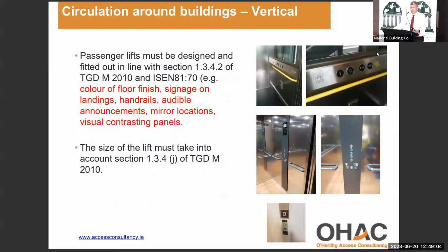Looking at lifts then, we have a European standard on lifts. It's adopted in Ireland. It's I.S. EN 81-70. That means we can buy a lift in Germany, ship it over to Ireland and install it. What we find on projects, though, is that there are 4 or 5 key elements that are in TGD M that are not covered in